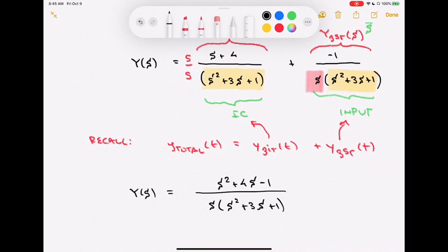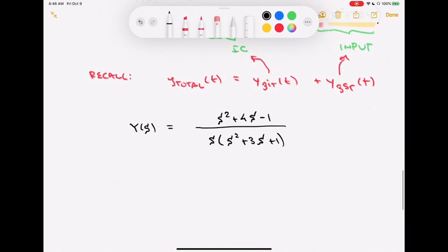So this is an expression. It's a rational function expression. This is very common for differential equations. I'm going to get this rational function expression that describes my total response, y, in the transform domain, so y of s. To get the solution I need to inverse transform this. So I do have those extra steps when I do transform domain analysis. I have to take both the forward transform and the inverse transform. The advantage, though, is that in between those two, I just have algebra to deal with instead of all that other stuff we did back in chapter 2, the convolution and all that other difficult to remember stuff. Notice here, too, I'm getting a solution, and I never explicitly found the unit impulse response. It's just coming through in the math.